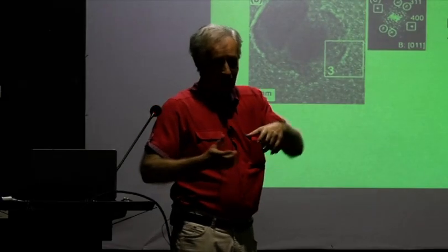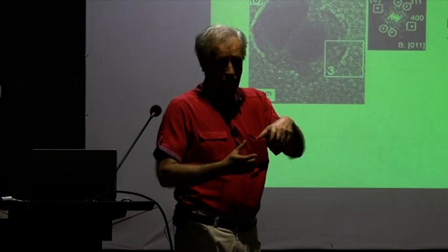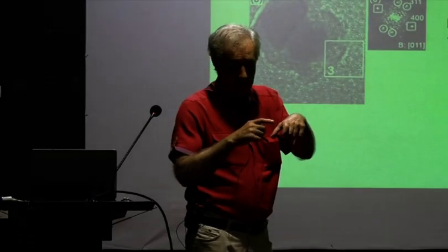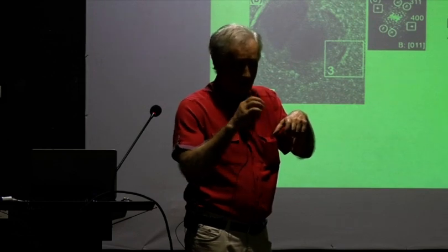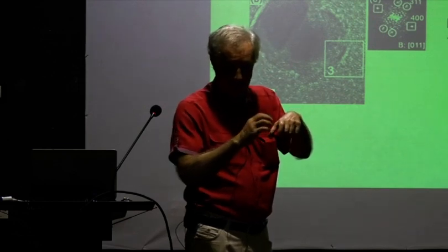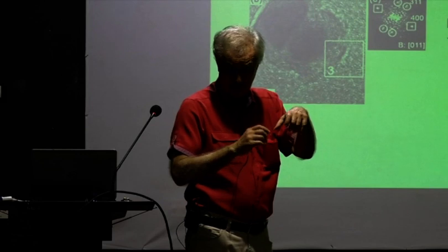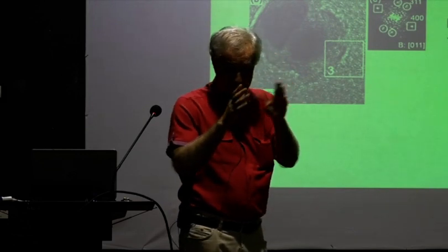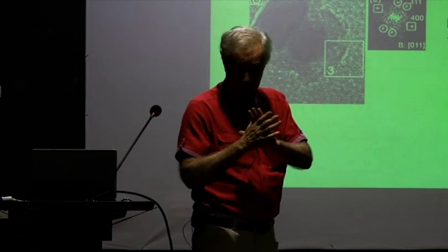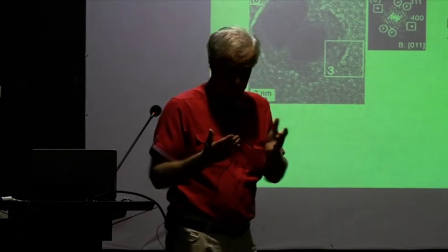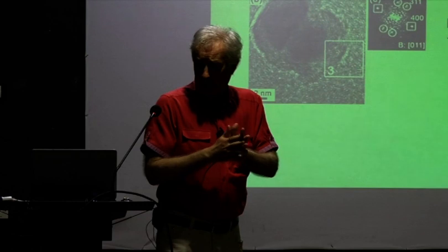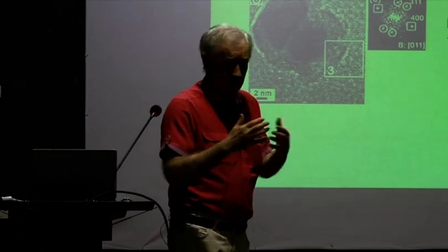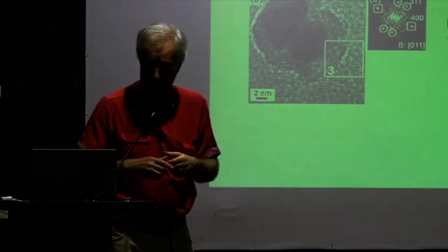How do you make iron silver? We have a single target, okay? So you take an iron target, you drill holes in it, and then you attach silver, and you press silver into those holes. And you hope that in the plasma you'll get iron silver of some kind. That's how you can do it with a single target. And now iron and silver, they don't mix at all. And it's very difficult to mix them.